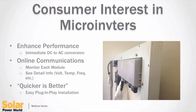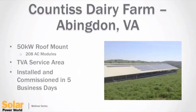The AC panel is one of our most popular that we've had. We've installed both microinverters and AC panels. What we like about the AC panels is that they're attached to the panel at the factory, which eliminates the grounding of doing the microinverters and the panel separately. They convert the DC power to AC right there on the panel, and it makes a much quicker installation.